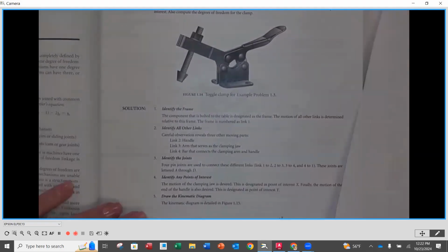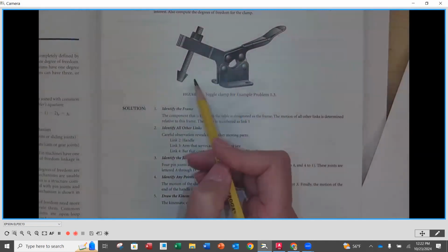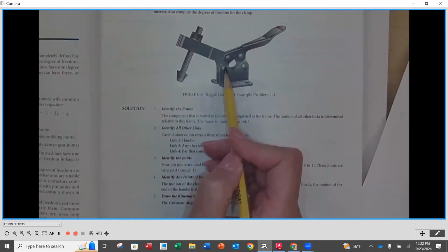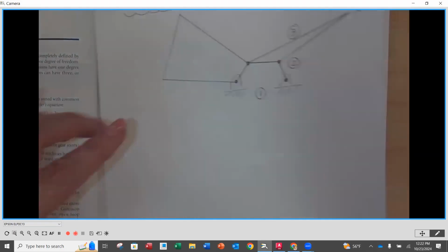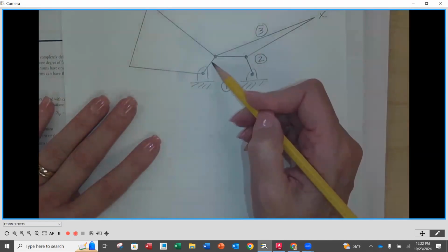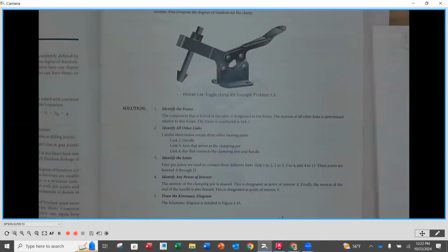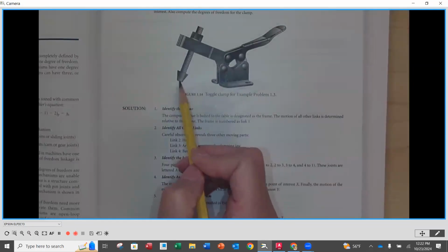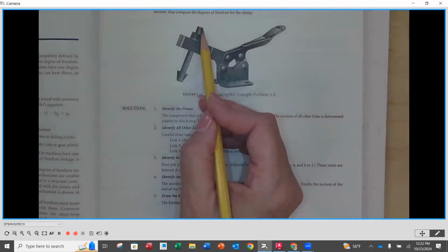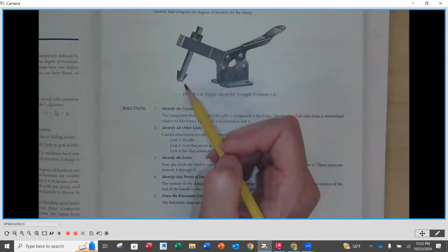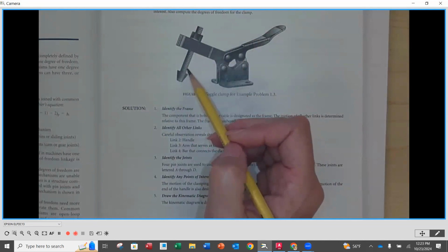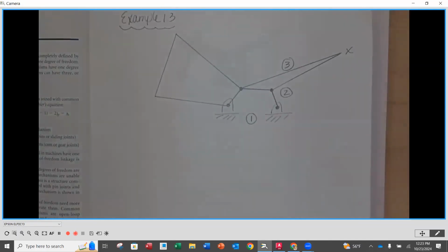Okay. So what I did was, here's our connection to the frame. And then there's the point of our connection with the handle, so that's just this line right here. But then it has the other stuff out front. So why did I choose the shape I did? I felt where the clamp is, where it's actually physically going to push down on an item, I want to know where that is when I'm designing. The other thing I want to know is how high this is, because I want to make sure as it rotates up and back, that it's not hitting something else. So that's why I chose the shape that I did.